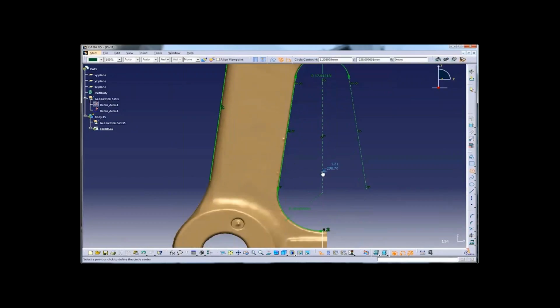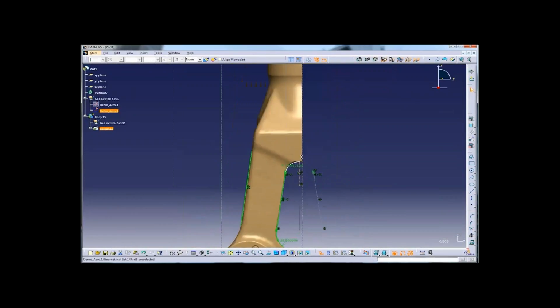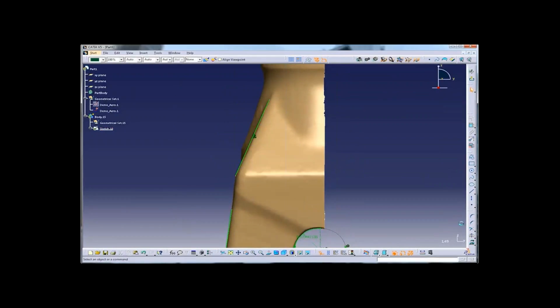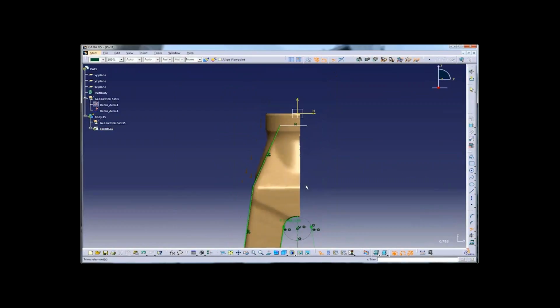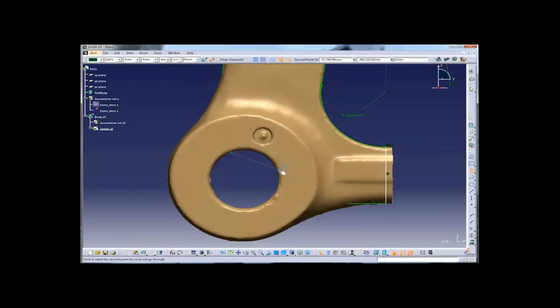As I said, there are more ways of creating sketches and more accurate ways of doing so. One of them is to create anchor points on the mesh, or to create a sketch from cross-sections. Cross-sections can be created in third-party software or straight from within CATIA. For more complex surfaces, there is also the Power Fit tool in the QSR workbench. This tool creates a NURBS patch from a selected mesh area.